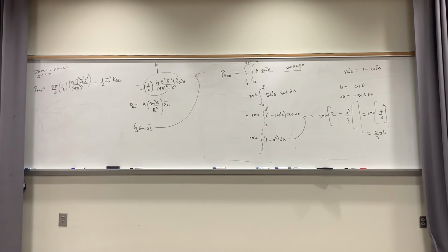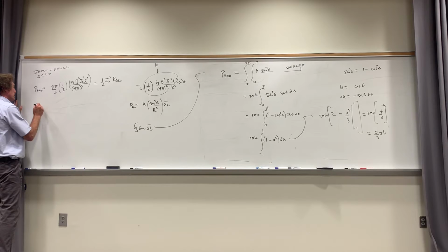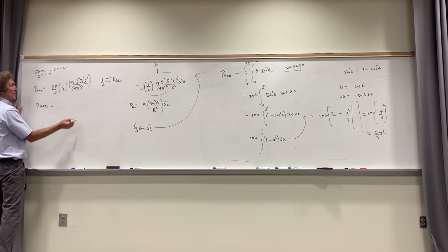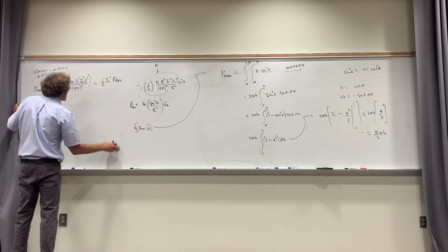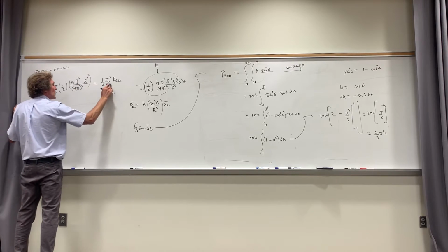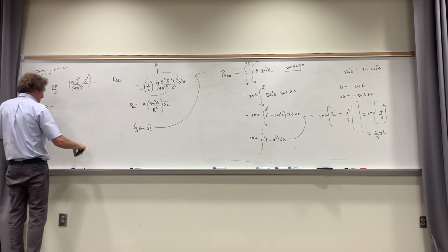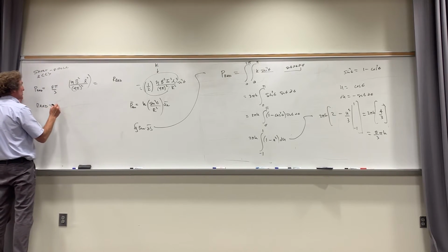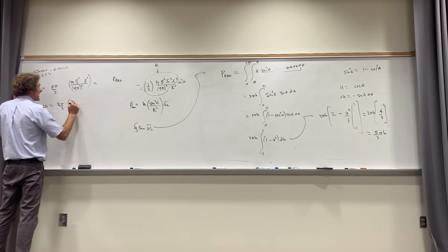It's just the way it is. We call them photons. So when I look at this, what is R rad for that one? Well, you all see how I naught appears in both places? Agree, class? So I get rid of I naught, and you all see how 1/2 appears in both places. Yeah. So I'm just going to get rid of I naught here, and I'm going to get rid of 1/2. I'm going to show you something. So this is our R rad. It's 8 pi over 3 times eta.